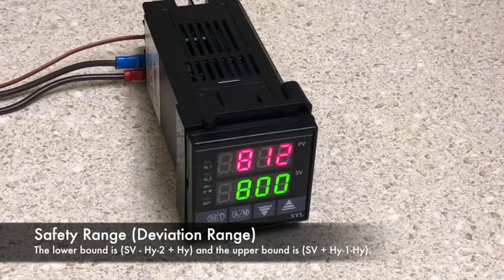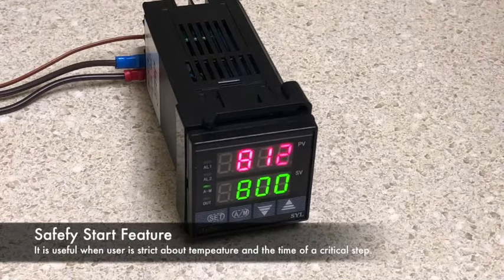At the beginning of a step or when powering up the controller, the program will be put on hold if temperature is out of the safety start range. If the temperature falls within the safety range, the timer of the current running step will start counting. Once a step starts running, it won't be put on hold, even if the temperature falls out of the safety start range again. The safety start feature is useful for when the user might need to be very specific about the temperature and the time of a step.